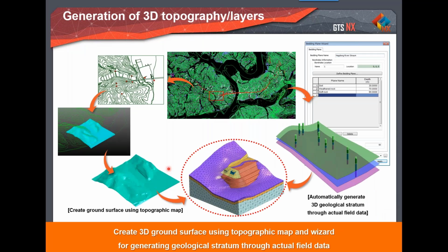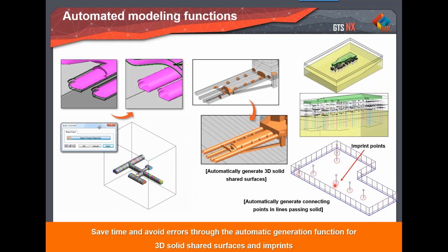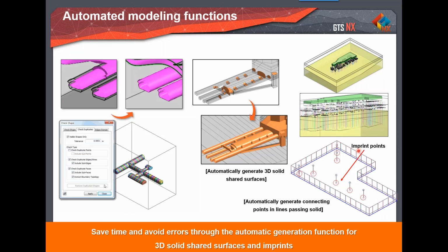And then we have an imprint option. Suppose you're dealing with piles and you want to model the pile as a beam element with some normal and shear stiffness. In such a case, you can simply use the line element, and that line element should be interconnected with your solids by using this imprint option.